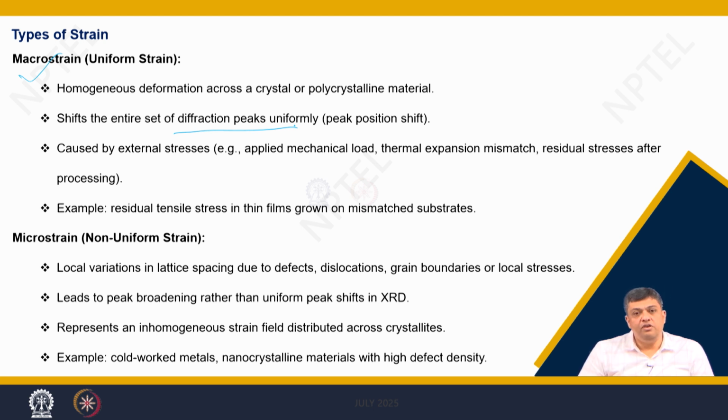Sometimes we can say that if there is a uniform shift in the diffraction peak, then it can be due to instrumental error. But if the instrumental error is eliminated, then in these macro strains you will find that the whole diffraction pattern would be shifting uniformly.